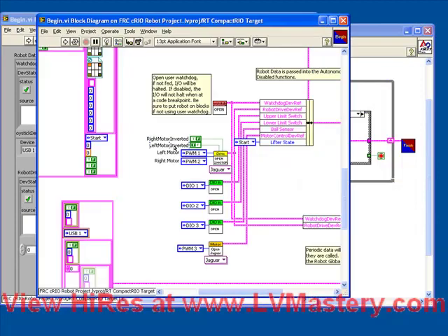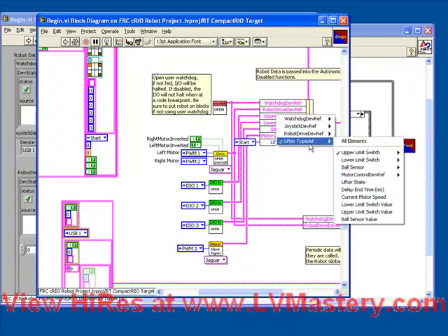In the begin step, we opened up 3 digital inputs and a motor controller and wired all of them into a type def which we created specifically for our lifter. That lifter type def contained the device references for the hardware, as well as an internal state, an internal delay timer to keep track of when to move to the next state, as well as keeping track of the output values, the current motor speed, limit switch values, and the ball sensor value.